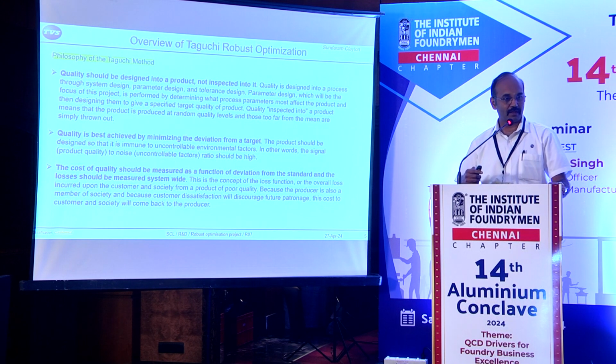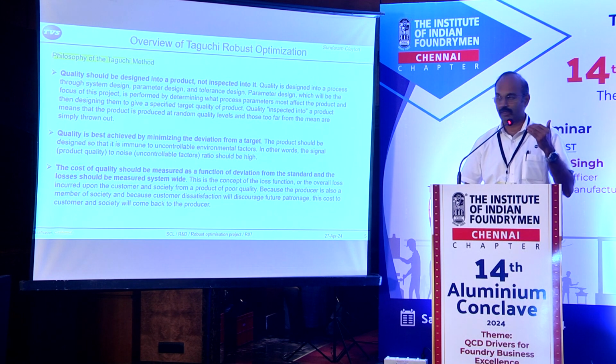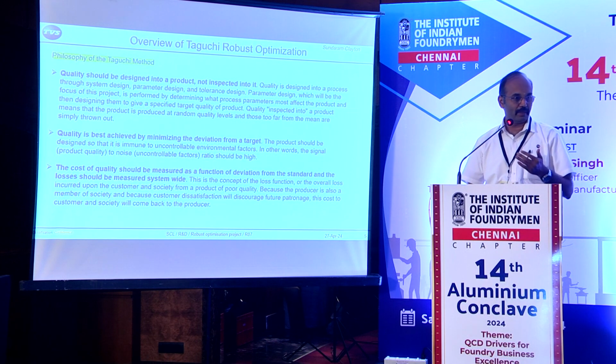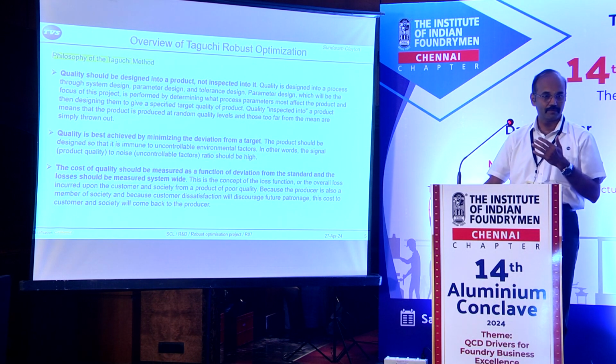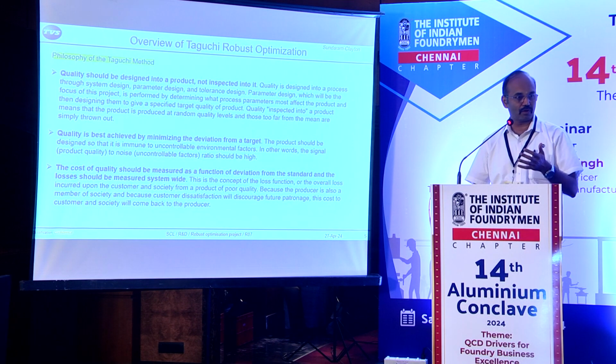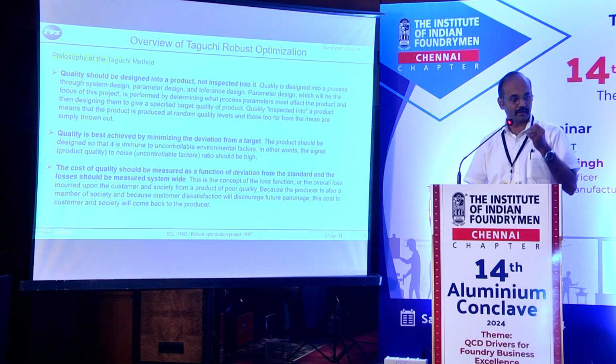His philosophy is that quality should be designed into the product and not inspected into it. He asks all the people who follow his techniques not to use this technique for firefighting. In the initial design stage or the product development stage itself, we have to use this robust optimization technique so that we develop products which, when introduced into mass production, produce the right quality of part.